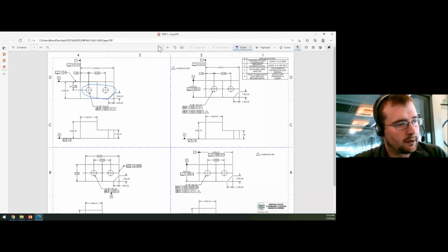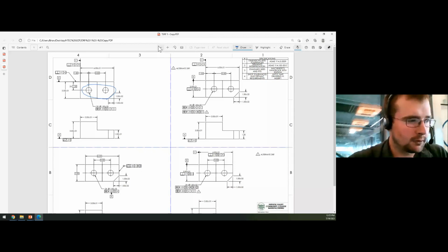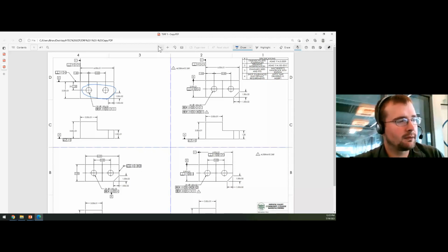For some reason, once we get past the datum system, and we get into how to create the datums and then fixture to it, and the 3-2-1 rule if they're planar and things like that, by that point in their education, that's a huge step. Machining students are always constraining the 6 degrees of freedom anyway. So when you bring it in wording how to fixture something, and word it as if it's a datum reference, what you're constraining to what, in what way, that has been the ticket in my experience.